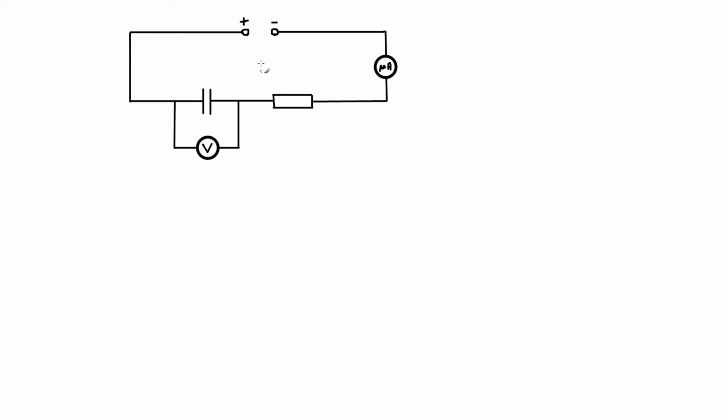Why was that occurring? Well, first of all, why could a current flow in the circuit? Remember from the construction of the capacitor that between the plates we have an insulating material. We've learnt that we need a complete circuit for a current to flow. So how is it that we have a current at all in the first place? Well, what's actually happening with these very large plates, very large surface area, is that for a short time a current can flow because charge can flow onto one plate of the capacitor and off the other plate.